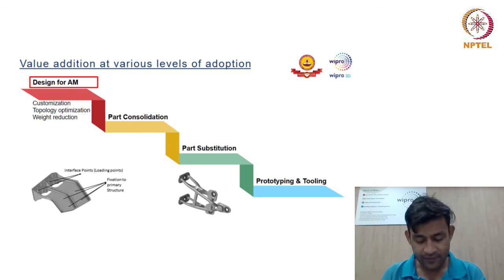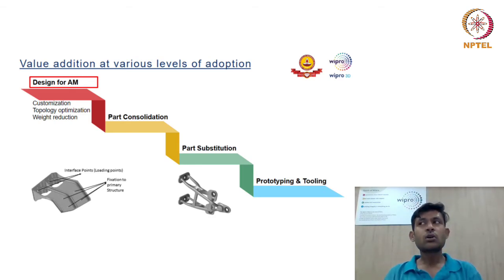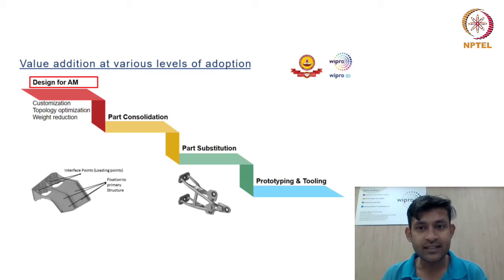They also have an understanding of how the additive manufacturing process is going to affect their end application, whether in terms of surface roughness, or quality of the component, which can be measured in tensile strength, or if the component sees dynamic loading, then we can also talk about strengths such as fatigue strength, impact strength, and other factors such as the geometrical dimensional accuracy of the process.